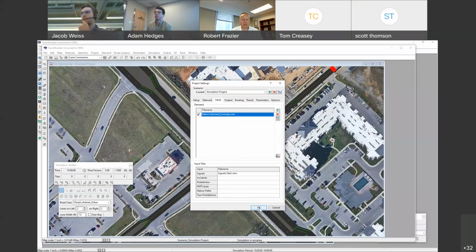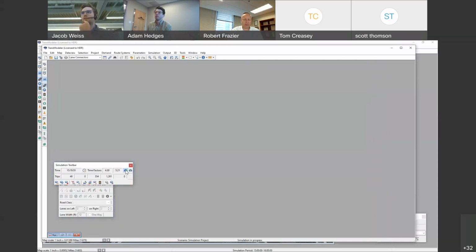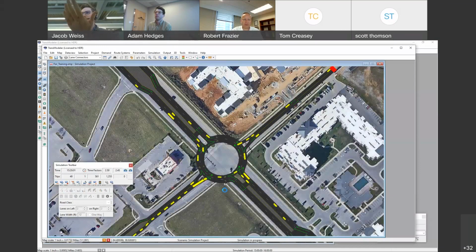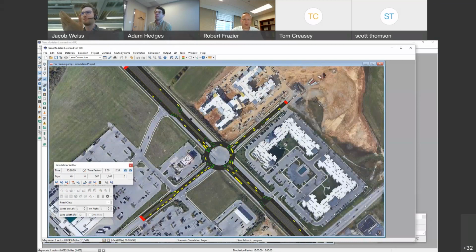So I'm going to click OK, and I'm going to run that simulation again, and we're going to go to 5:15 and look at how much extra demand is occurring. So as you saw before, there wasn't any congestion on this approach node from the southwest. Now, since we're showing 40% of that demand with essentially a very low peak hour factor, say everyone's trying to leave Costco at the same time, that would show up as the congestion at this location.